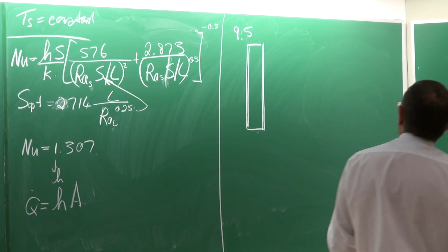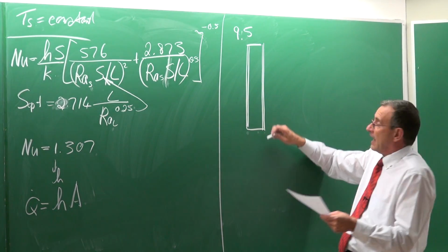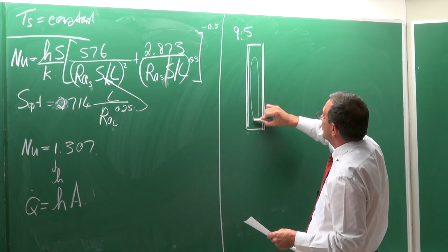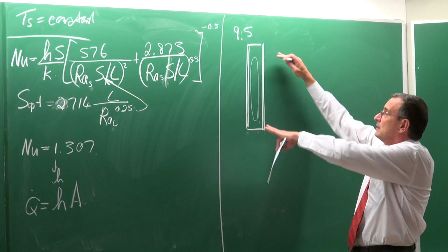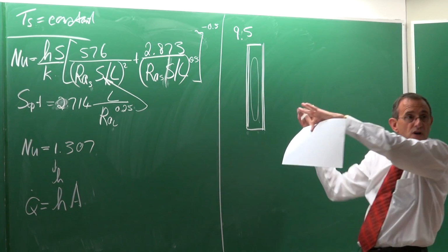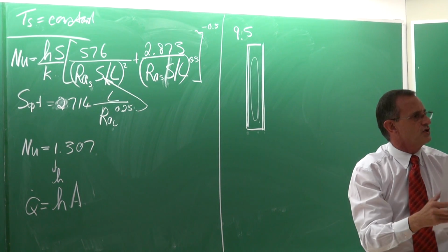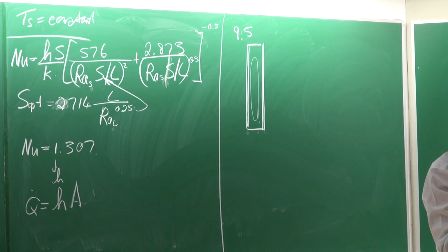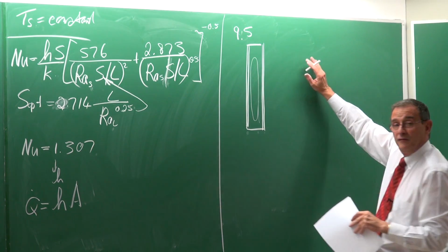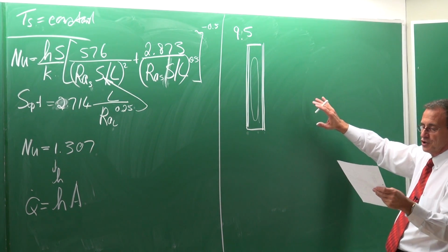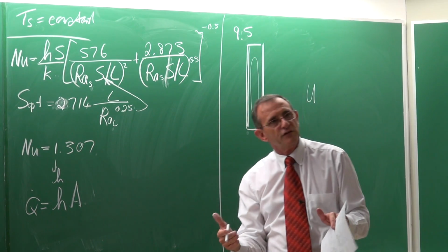Okay. So normally, in many cases, you've got two glass panels there, and inside that, you also have circulation. And again, the angle would determine how much circulation you have, and there are lots of equations in your textbook. We are not going to go through all of them. But this, if you go through it, reduces to, at the end, something where they get the overall heat transfer coefficient,